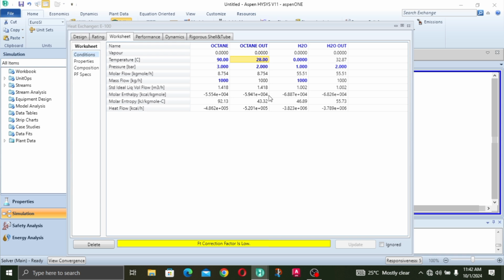So this is basically the heat exchanger doing its operation of transferring heat from a hot stream to a cold stream. The hot stream loses its heat and the cold stream gains that heat lost. And the factors which affect this majorly in ASPEN HYSYS are the change in temperature and mass flow rates. The specific heat capacity also does, but it's something a bit more complex for the scenarios to bring in. But hopefully you might see that in the future. So let's just correct this. Let's make this 50 Celsius. Yeah, it's perfect.